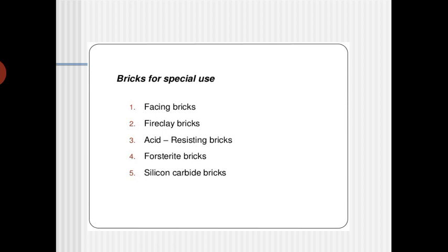you are using for 3 to 5 kg of bricks, normally we have to use 5 to 10% of alkali related to that. So if it is 5 to 10%, normally you have to give around 10 to 12 rupees of commercial grade of sodium hydroxide to this type of bricks.